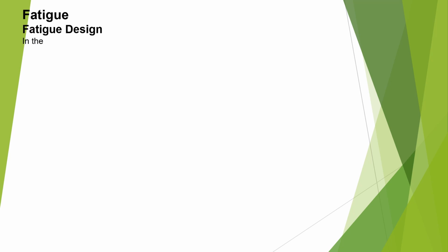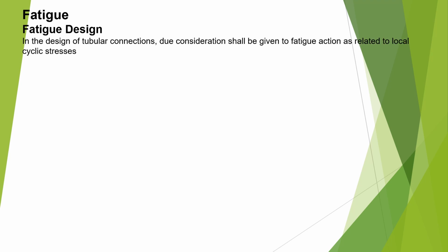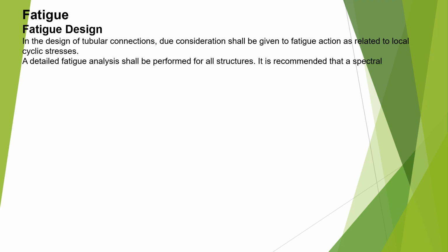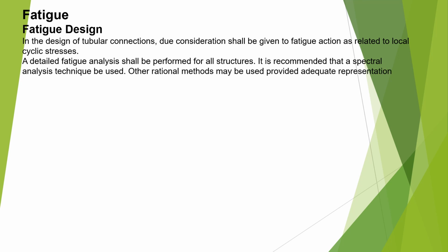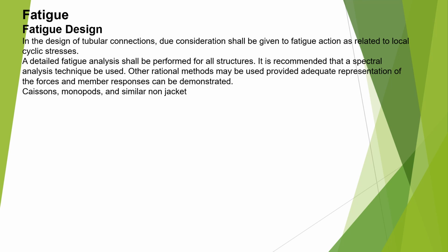Fatigue design. In the design of tubular connections, due consideration is given to the fatigue action as related to local cyclic stresses. Detailed fatigue analysis will be performed for all structures. It is recommended that a spectral analysis technique be used. Other rational methods may be used provided adequate representation of the forces and member response can be demonstrated.